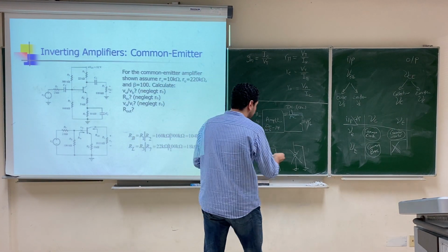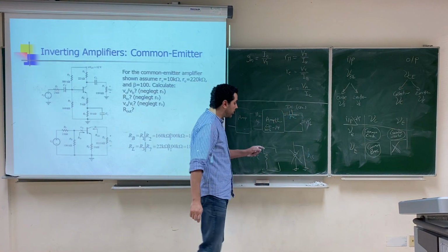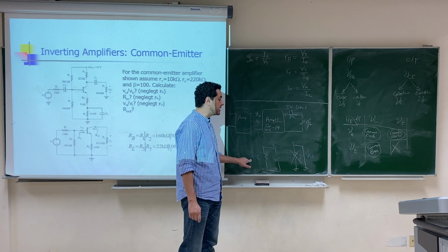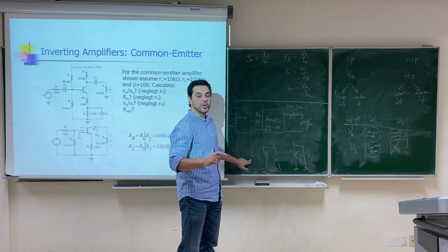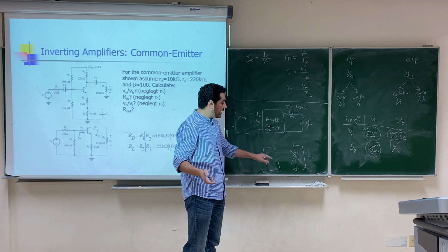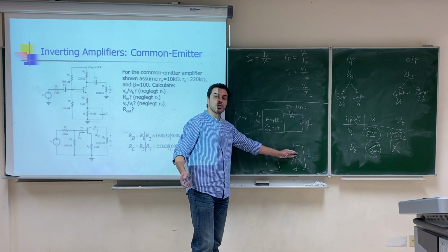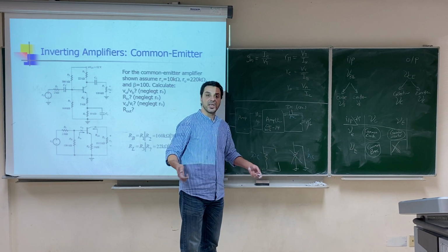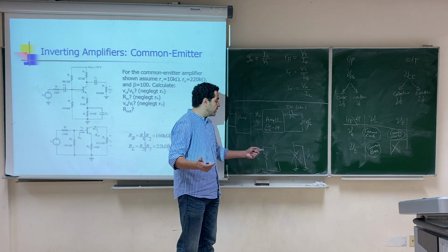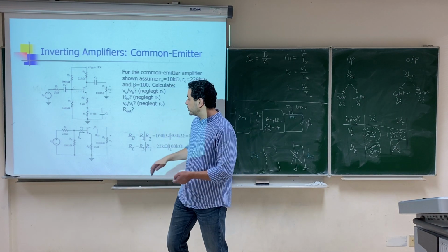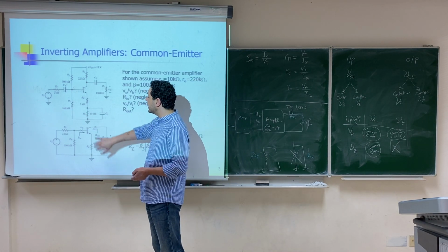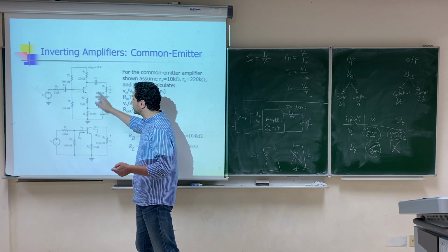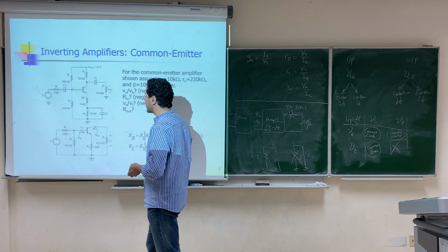So through the bypass capacitor, we can control that some resistors will appear in the DC analysis to control our bias point or whatever we want, and they will disappear in the AC, also for some benefits in the AC analysis, like increasing the gain. So bypass capacitors are useful to keep some resistors during the DC and remove them during the AC automatically. Okay, this is the benefit of bypass capacitors, and we already talked about the coupling capacitors before.